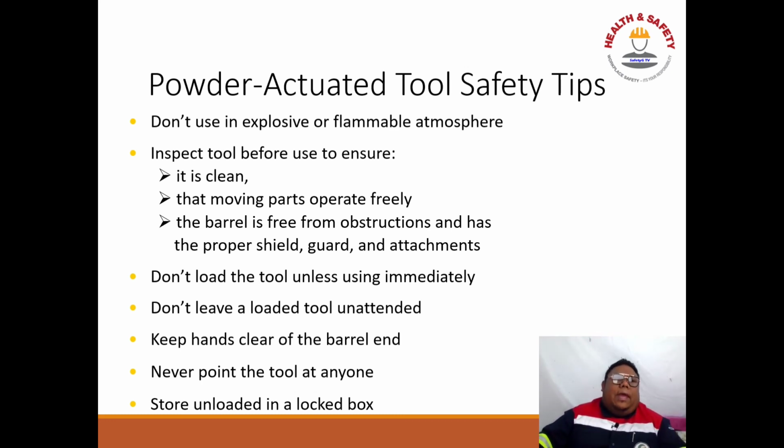Okay. Next is, don't load the tools unless using it immediately. Okay, take note on this one, guys. Don't leave a loaded tool unattended. Keep hands clear from the barrel end. Never point the tool at anyone. Store unloaded in a locked box.